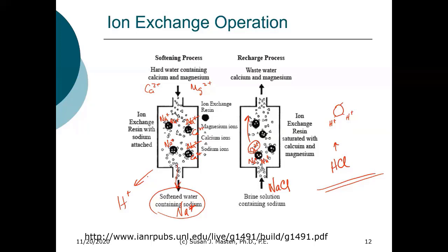So if you don't have sufficient alkalinity in order to buffer the system, you're going to end up with a treated water with a low pH. So we could, but we have issues with safety, and we have issues with decreasing the pH and resulting in increased corrosion, which also can be a safety concern because of the release of metals into the water.